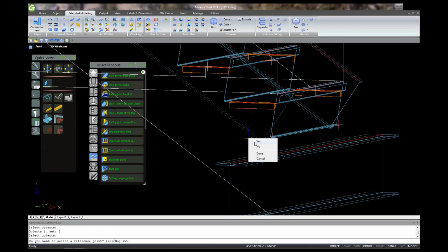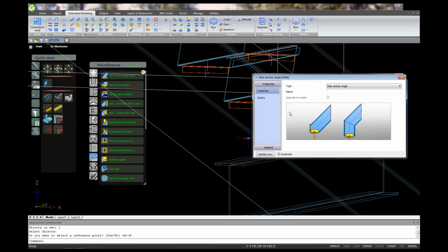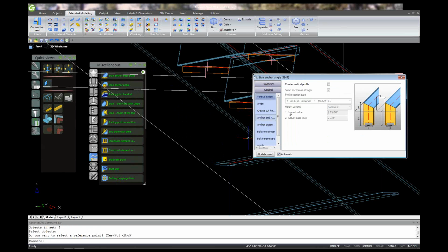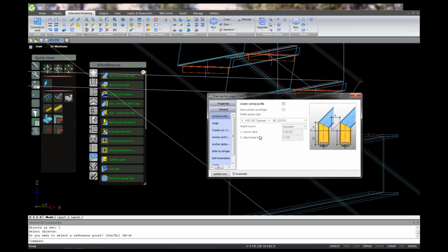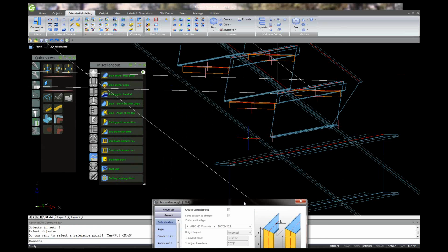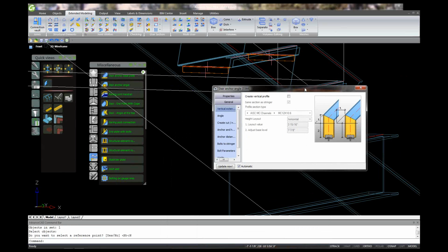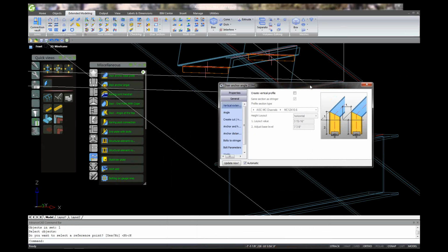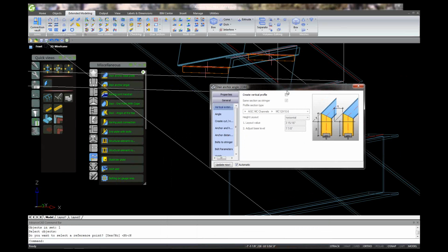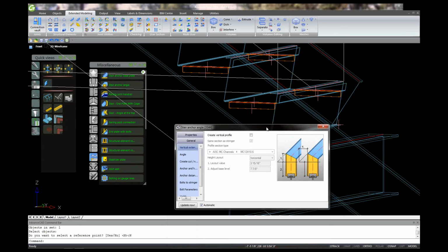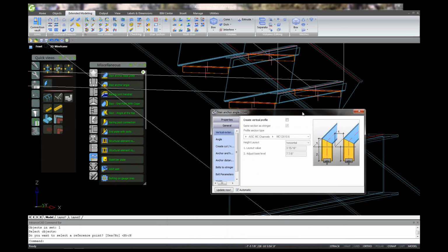Do you want to select? No. General. It's fine. See what it's doing? It's throwing the stringer way down there for some reason. Is that going to 0,0? Okay, your UCS. Hold on a second. That's my problem. Okay, you need to put your UCS to world. All right.